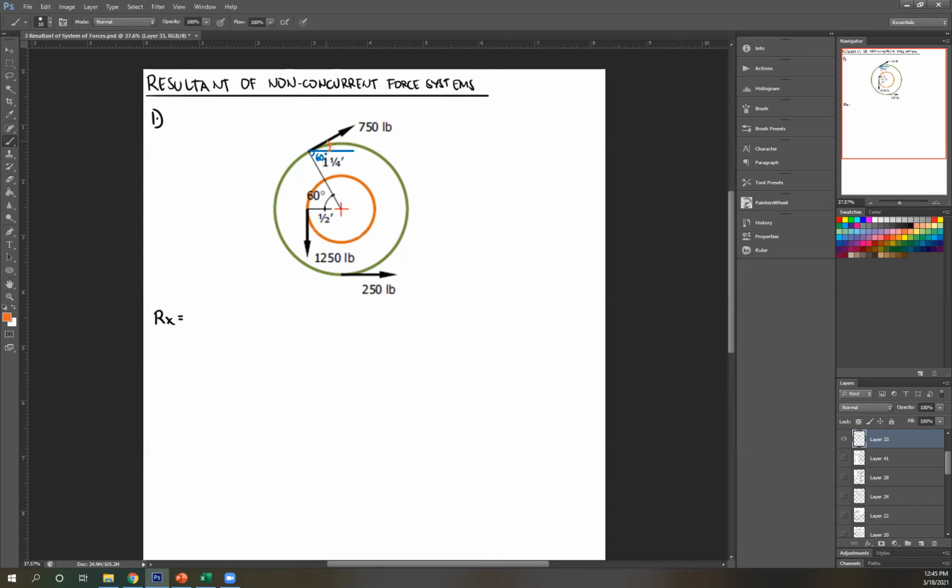And this 750 force is acting tangentially to your circle, denoted by this line, perpendicular to your force. So this line is perpendicular to this line, so this total angle is 90. Therefore, 90 minus 60, this is your 30. Well, let's choose a different color. Blue. And 30. Once again, why? Alternating interior angles. So this is 60, 60. These are right angles because this is tangential to your circle. So therefore, 90 minus 60, get 30.